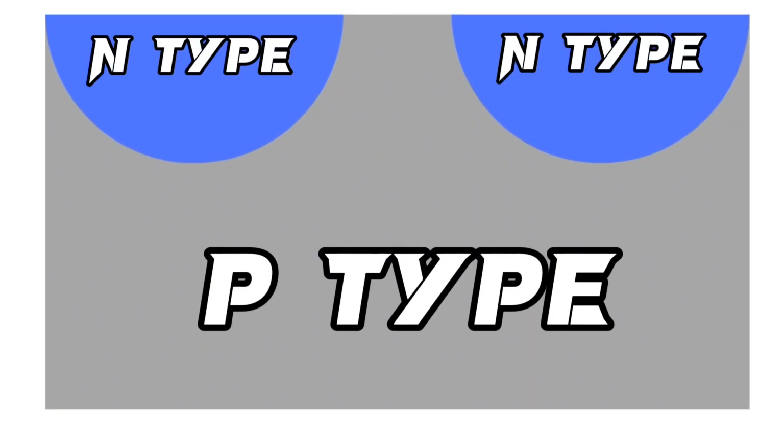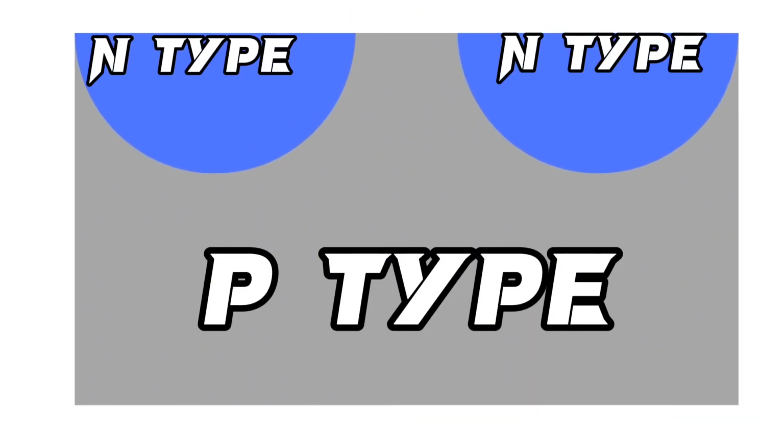To have a transistor, we need to add n-type doping to the other side. So if we have a structure like this, we've created a MOSFET transistor. But if we try to connect a battery to it, electrons will not move through it. To solve the problem, we need to add a metal layer with an oxide layer to the p-type. This is the gate of the transistor.